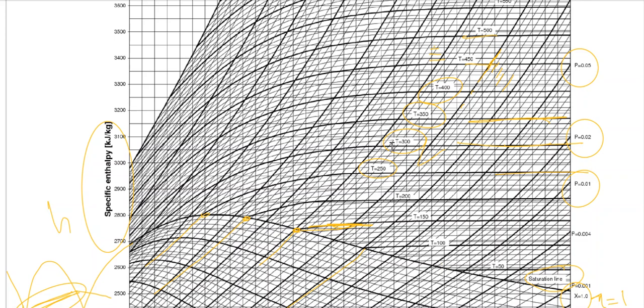Now let's move to the specific enthalpy over here. Let's say for example one of them over here. So these lines are divided into different gradients. 3200, let's say for example 3300 over here. So that means the line between them should be 3250 something. And if I divide it further, that would be 3275 something, and so on and so forth. So you can divide precisely, or with a ruler, you can just divide these lines anyway.